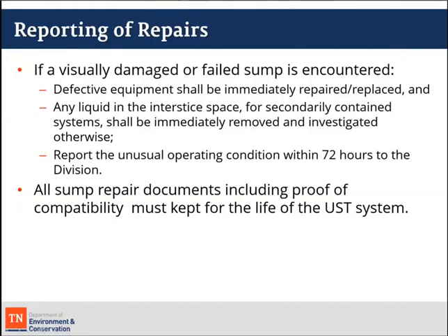If you go out and you have a sensor and alarm and you look and you've got water in your sump, you don't have to call and report that to us, but you do want to remove that water and investigate to see where that water intrusion is coming from. If it's occurring over and over and over, every week or every time it rains, then you probably do need to contact your field office and say, hey, we've got this issue. What do you want us to do? Likely we ask for an integrity test of the sump and then go from there.